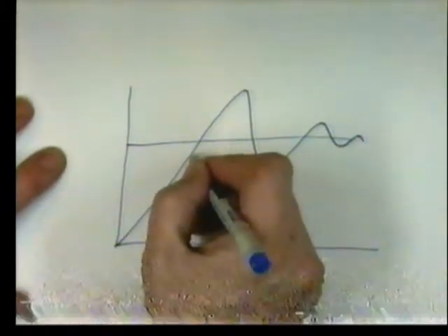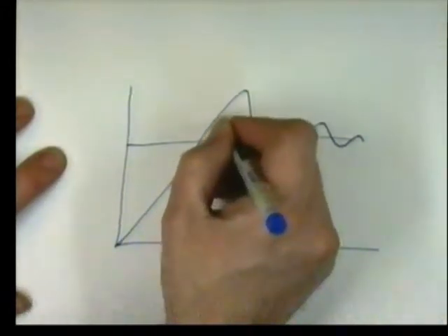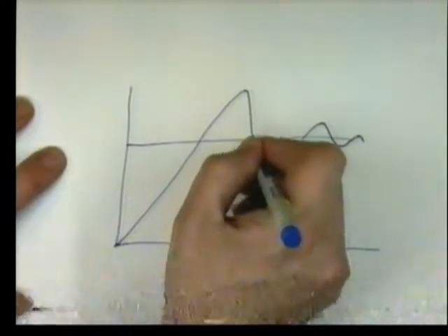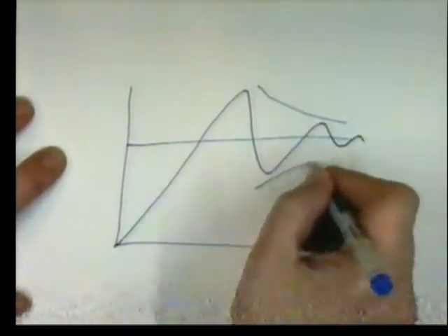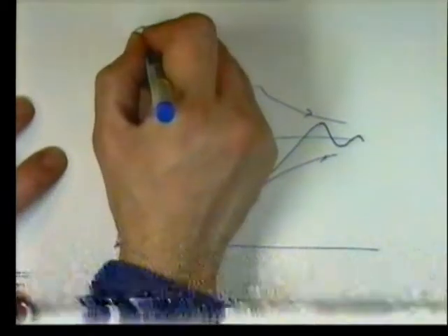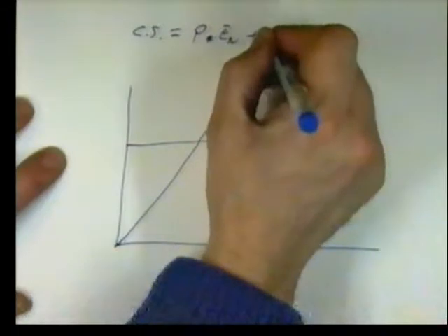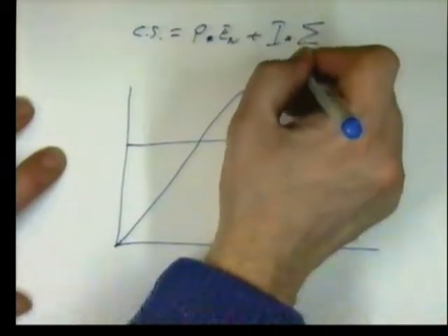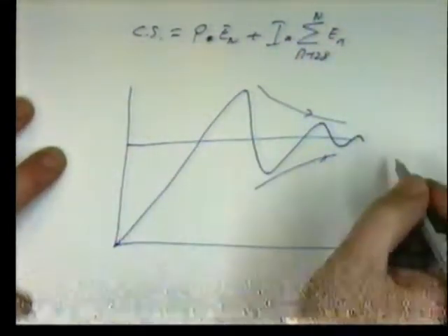What's happened here is that the steady state error has grown, the integral term has pulled us through the set point, the error has now gone negative, so the integral starts decaying, and hopefully we oscillate neatly around the set point with a nice exponential decay. This is the proportional plus integral control, and this is its characteristic response. Proportional plus integral control. And that's usually about all you ever need for the vast majority of control systems.